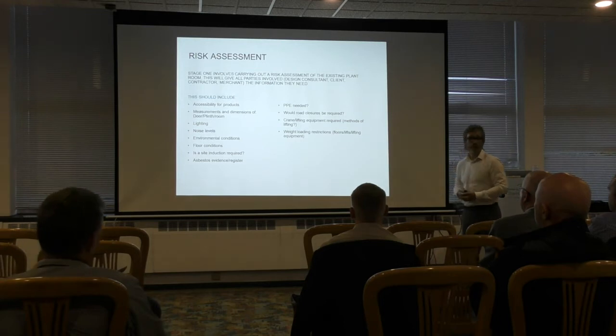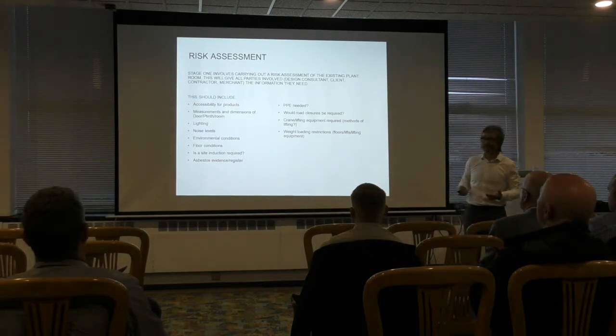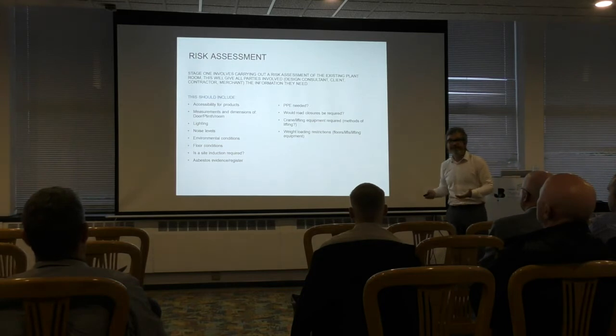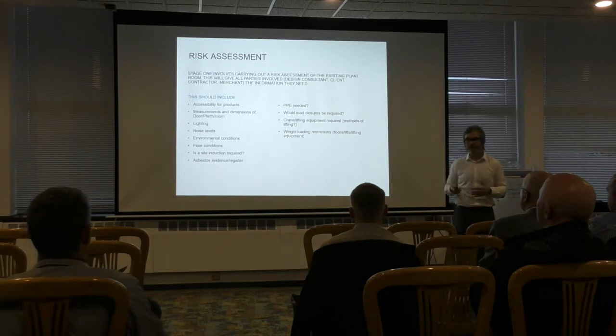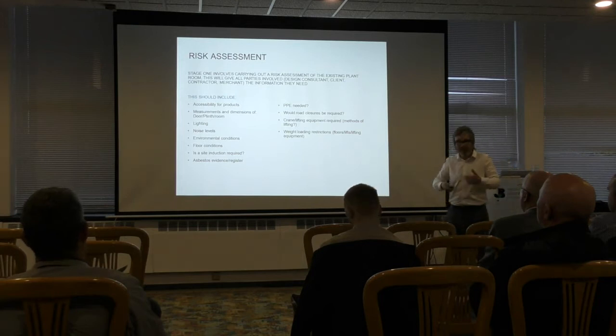So if there is anything important they need to be aware of, they can be highlighted. But really, a few pointers that we think you should be looking at on accessibility for the boilers themselves, pretty obvious I suppose: getting them into the plant room, also getting them out of the plant room as well. Going back a few years ago, it was quite common practice to almost build a plant room around the boilers with no consideration to plant room replacement strategies. Because now we have to go through that whole plant room replacement strategy process. Years ago that wasn't done.